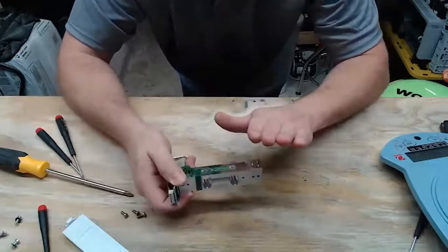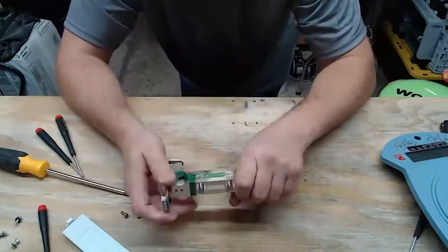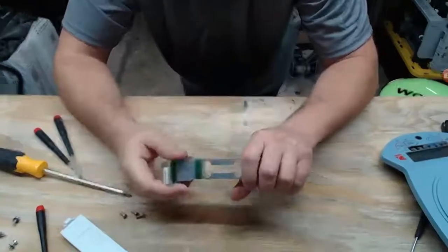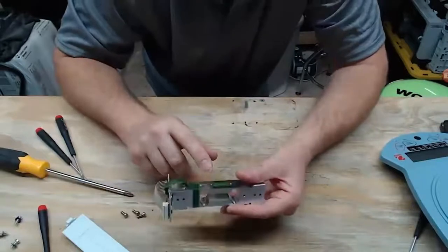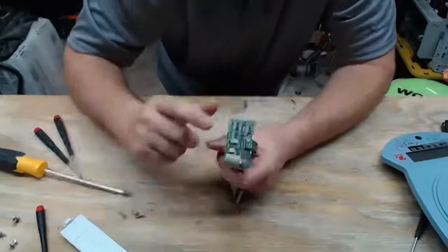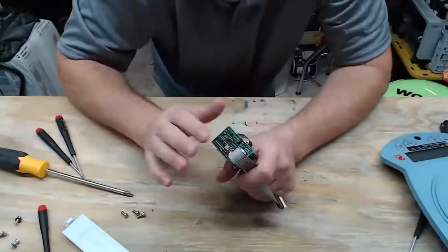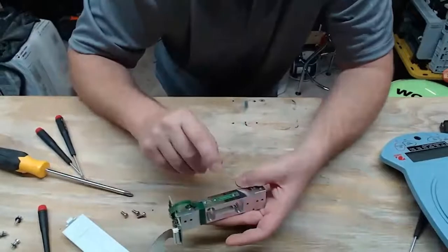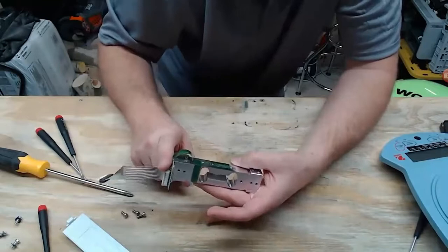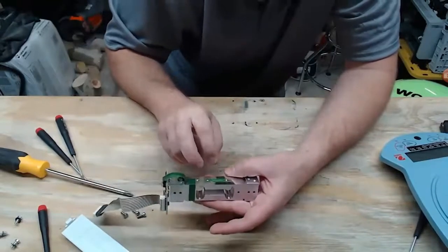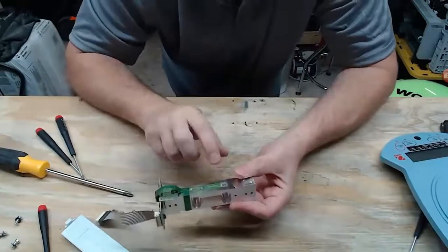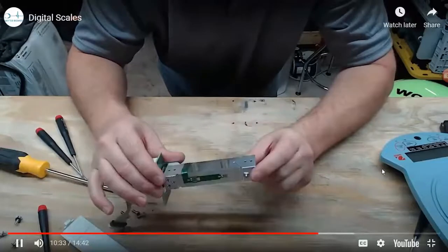Because as you add tension on one side and you get compression and expansion, that's going to change the voltage measurements. These are going to be an analog signal, and they're going to come here to a board that's going to convert them to a digital signal, which is why I was referencing that they placed the board that does the analog to digital conversion as close to your analog sensors as possible. So this is a load cell, and these are strain gauges. There are 4 of them.